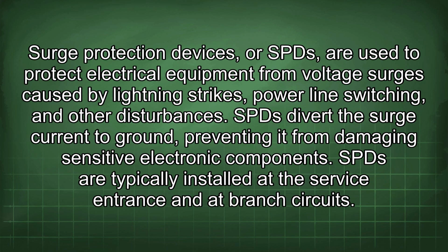Surge protection devices, or SPDs, are used to protect electrical equipment from voltage surges caused by lightning strikes, power line switching, and other disturbances. SPDs divert the surge current to ground, preventing it from damaging sensitive electronic components. SPDs are typically installed at the service entrance and at branch circuits.